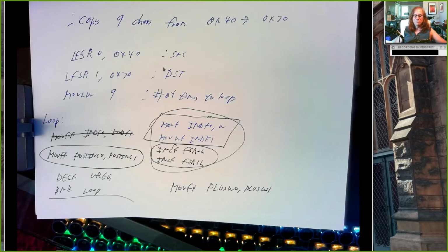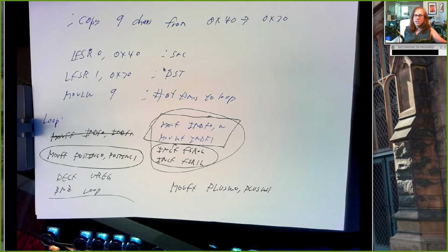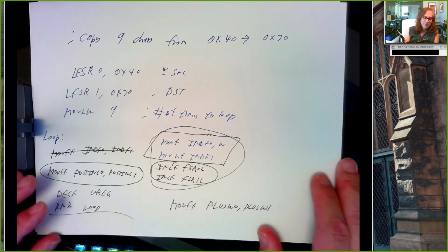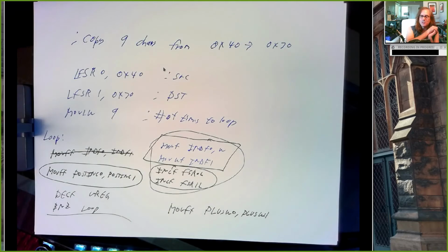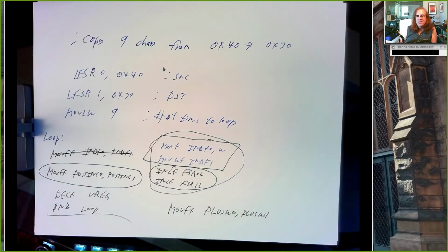But technically no. We happen to have 3 of these indirect register sets here. If we wanted to do something that involved multiple arrays, what we'd have to end up doing is store FSR 0 into a pair of temporary registers, and then read from another set of temporary registers back into FSR 0.